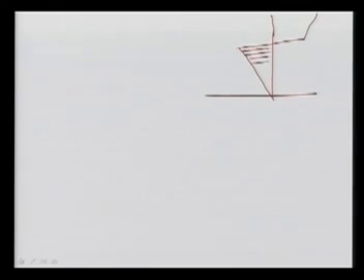The natural characteristic of SVC: normally we operate in this zone, then we have the slope, and then this one. So this is the operating zone where we have to operate our SVC. When voltage is more than this reference point, then we have to go into this inductive zone. This is your capacitive zone, and in this capacitive zone, if the voltage is less, then we have to provide this. So this is the VI characteristic of the SVC.